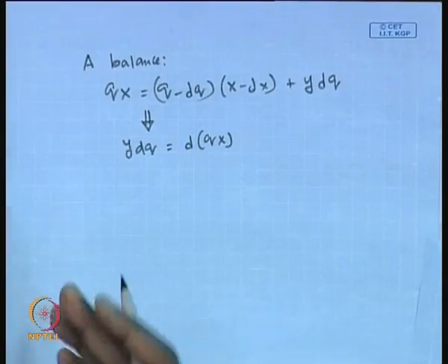The local flux will be the permeability of A divided by the thickness multiplied by the delta P. Delta P is the partial pressure of A in the feed side minus partial pressure of A in the permeate side.